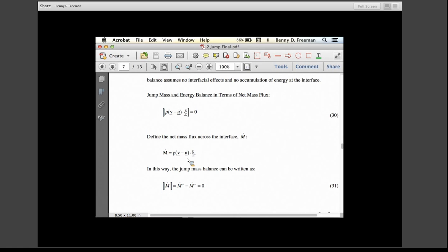Just because you pick the glass up, the rate of evaporation that you calculate shouldn't change if you just pick the glass up and put it from one table onto another, right? And so the mass flux across the interface we're after is the net mass flux above and beyond the motion of that phase interface. This would be for a liquid gas system. This would be basically in the gas phase, the rate of evaporation of that liquid into the gas phase.